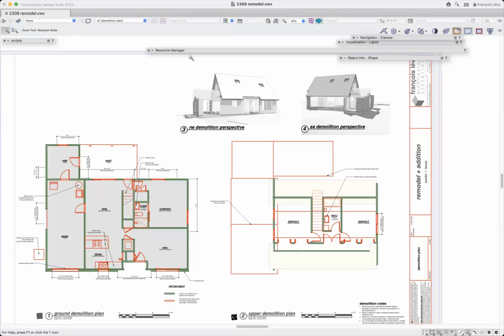Well, I find that what you talked about in terms of partitions and moving walls and removing walls and putting a door, creating an opening, I've never done that before. That solves a big problem. Create the opening first and then put the new door in it. A silly question, but if I was to do that, I would make the hole the size of the rough opening for the door that I'm putting in there, because the new door will not be connected to the wall like they usually are. It's not an insert in the wall, right? Right. It's a placement.